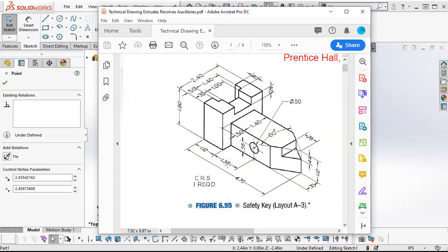So if we're going to go through and build those numbers out, then it's going to affect our tolerances. Do we need the tighter tolerance? Is this going to be a plus or minus 10 thousandths? That's something that we're going to build into the title block, and we need to take into consideration.